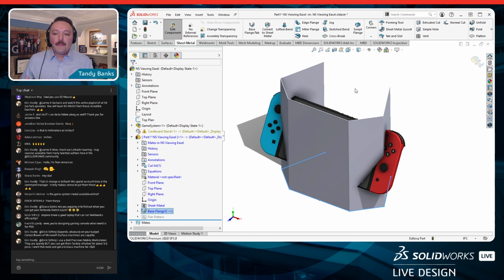If you ever download models, especially if you're doing real work, if we're actually building some real geometry, always verify the dimensions. Horror story real quick, I designed a large skid around a hydraulic pump that I got from the manufacturer. Actually, I got a model from the manufacturer, designed my skid around that, and whenever it came time to produce it, the model didn't match the actual real life part, and I had to redesign a lot of stuff. And so from that day forward, that was my lesson learned. I got burnt, and so anytime that you're downloading models from somewhere else, always verify the dimensions.